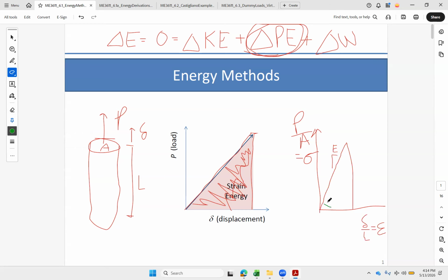also represents a form of energy, but it's an energy per unit volume. It's called strain energy density over here. Usually it's going to be a lowercase u for this one and a capital U for this strain energy over here. But strain energy per unit volume. We took a force per area, so now we're per area. We took our displacement and did it per length, so now we're times length. And I could see A times L gives me the volume that was inside.